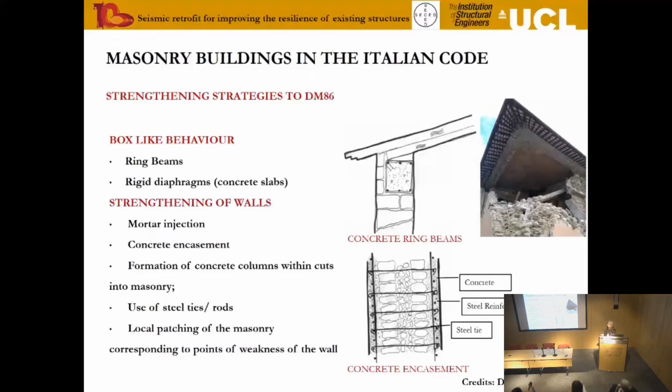There would then be a rigid diaphragm, because as you have all learned in your seismic design studies, if the diaphragm is rigid, we can assume that the structure works like a one degree of freedom system, and our life is very easy. So yes, let's put in a rigid diaphragm. And the rigid diaphragm would, if it works well and if the stiffness is evenly distributed, prevent single parts from moving differently from the others. So also a good idea.